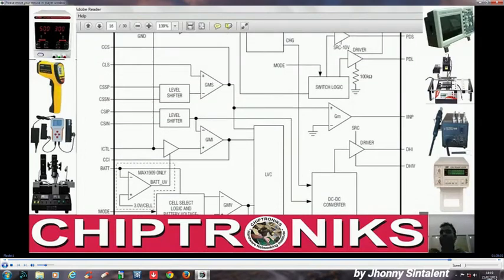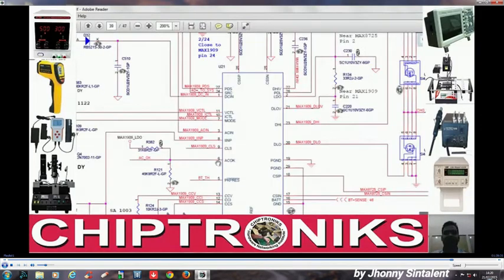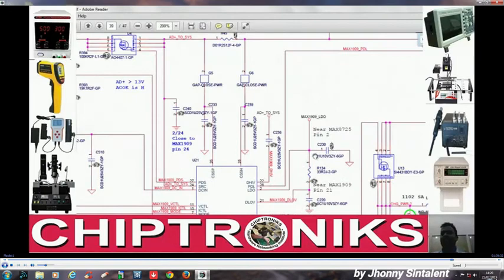So if we are checking such a scenario, I will always advise to first remove the battery and try a new battery. We'll use this concept to discuss practical cases like battery working, adapter not charging; adapter charging, battery, adapter okay, battery not charging; plugged in not charging. All cases can be solved if we understand these important signals. Understanding these important signals is very important.